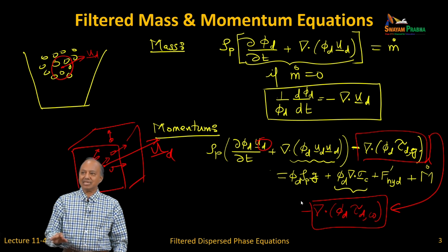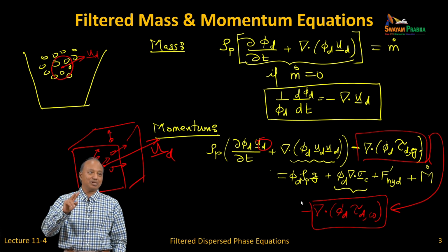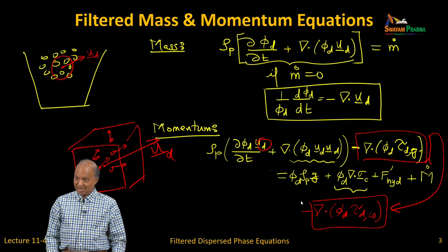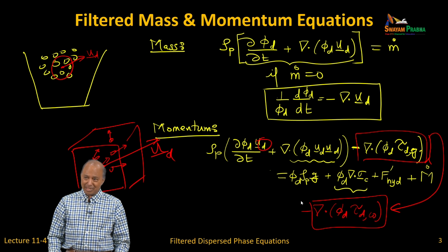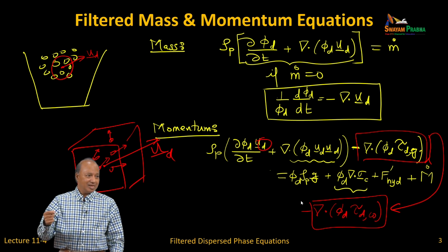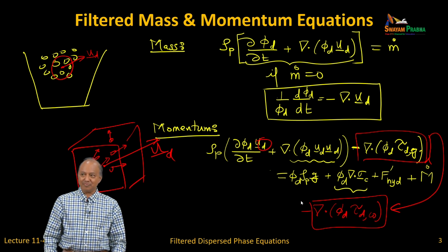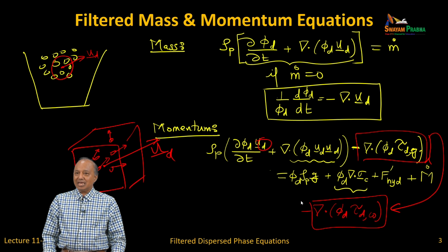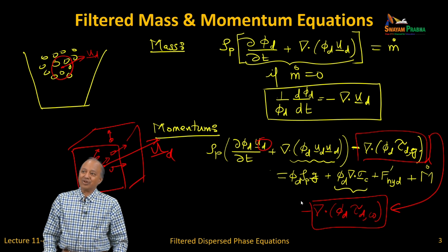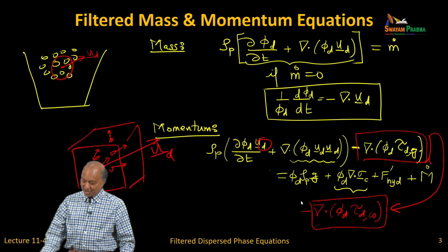That is what the kinetic theory of gases people do. There are two kinds of temperature equations people use in Euler-Euler methods. One is the normal thermodynamic temperature, heat transfer, etc. The other is what is called granular temperature, because of particle velocity fluctuation.